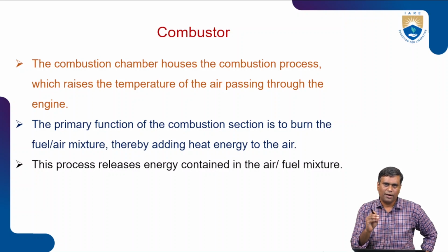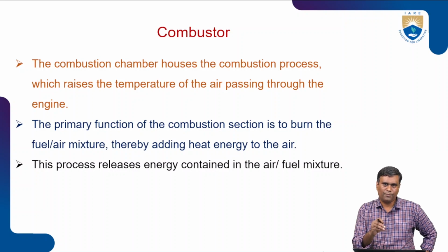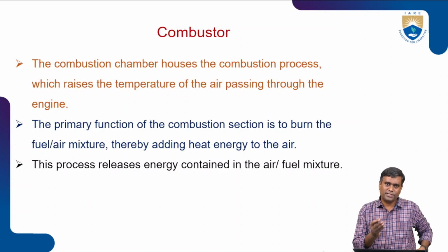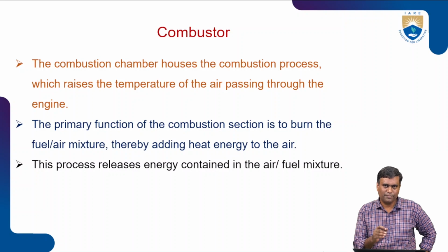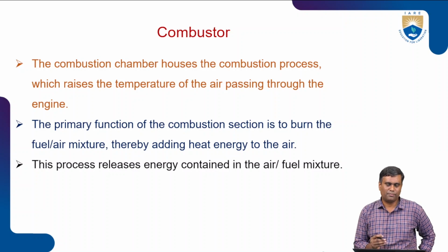That is the reason a diffuser will be there in between the high pressure compressor and combustor, where it decelerates the airstream and increases the pressure, and that decelerated and increased pressure air will enter the combustor, and through the injectors in the combustor, fuel will be added.